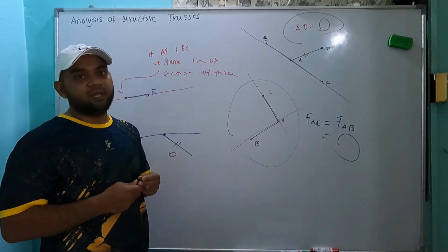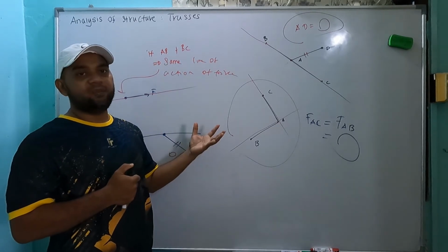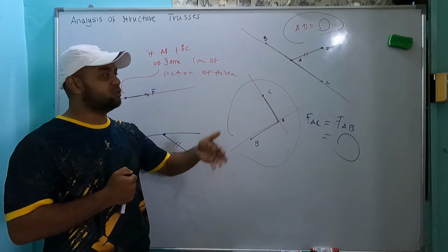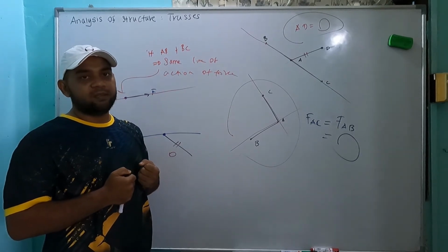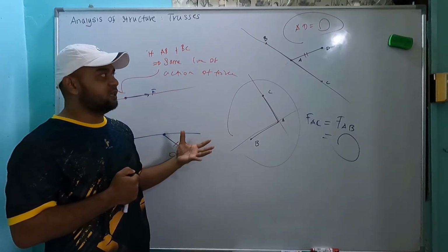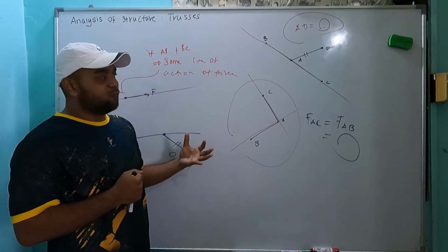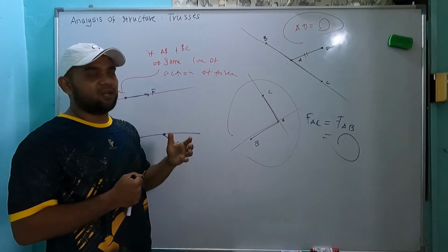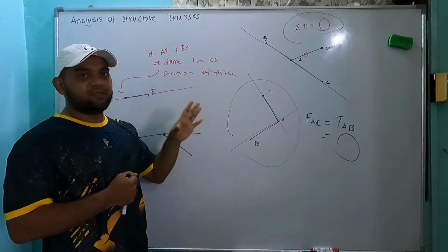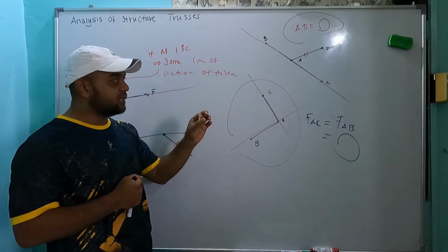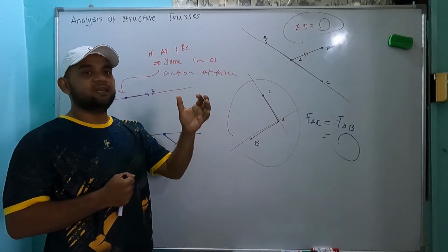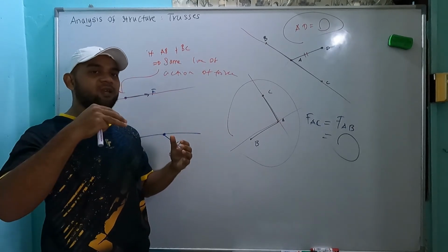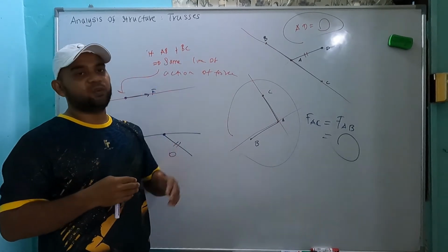So some of you will ask why we maintain this component. It does not exert any forces, so why is this component there? We should directly put it away. Why we still maintain that component is because at that specific loading condition, that component didn't absorb any forces. But if the load comes from a different angle, that component will function.